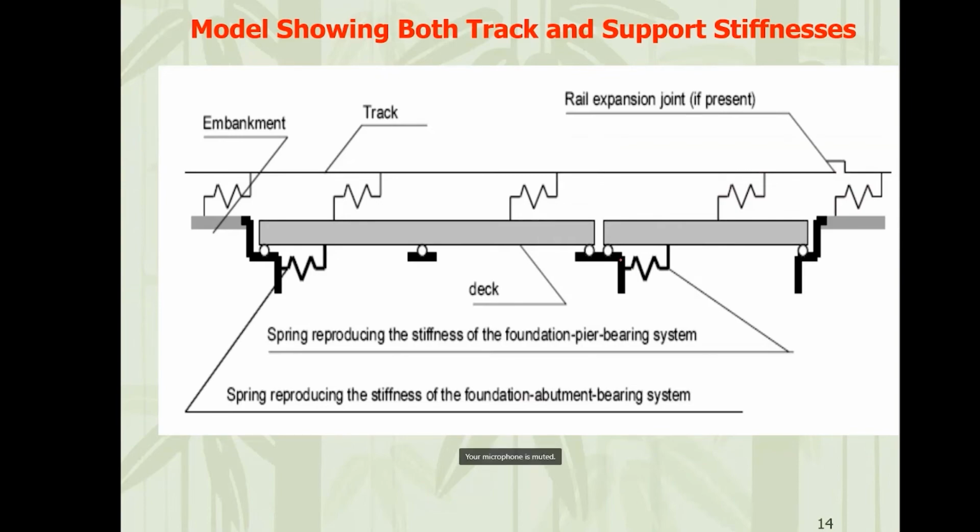Okay. And span, for example, here this span length is this. Because of the span, which interaction effect is going to be controlled? Deck bending, right? Because bending will take place over the span. If the span is small, bending will be less. For example, here these are the individual spans, so deck bending will be controlled by the spans, but the thermal effect will be controlled by the deck length. Okay, so this way we have to differentiate, and these are the ways and means available to optimize the designs of these structures. Okay.